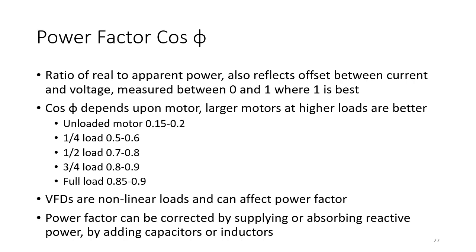You've got a combination of the current and the voltage, they combine. But what happens with motors is, because they're non-linear loads, they can affect power factor, and so can VFDs. So what you'll find is the current becomes offset from the voltage cycle, and that can cause problems on your power supply. It can be corrected because you can add either absorbing reactive power, you can do it with capacitors or inductors, and you can also supply reactive power as well, and you can maybe offset different types of motor with each other to offset the different loads there.